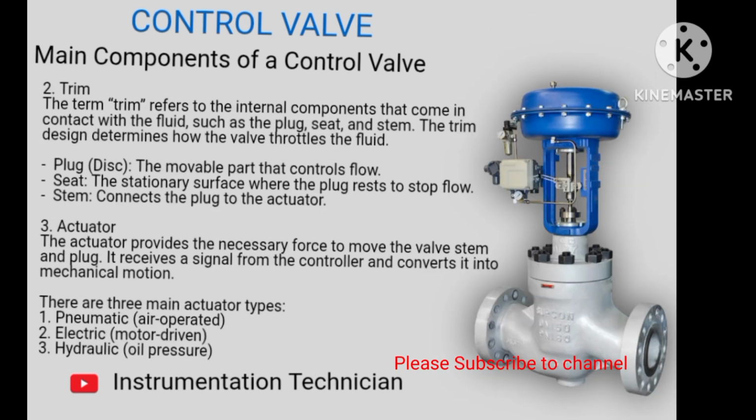2. Trim. The term trim refers to the internal components that come in contact with the fluid, such as the plug, seat, and stem. The trim design determines how the valve throttles the fluid. Plug, disc: the movable part that controls flow. Seat: the stationary surface where the plug rests to stop flow. Stem: connects the plug to the actuator.